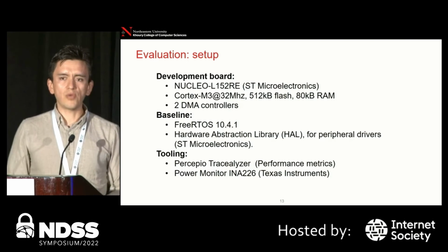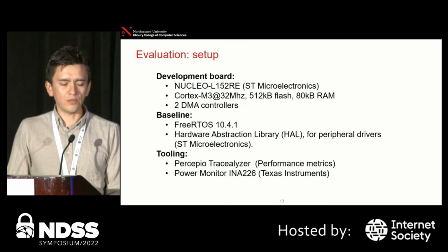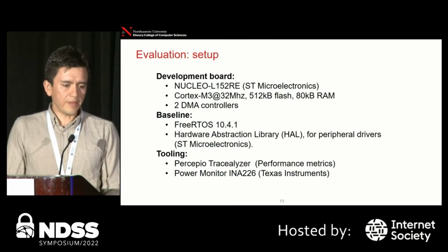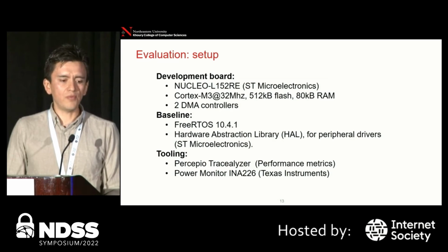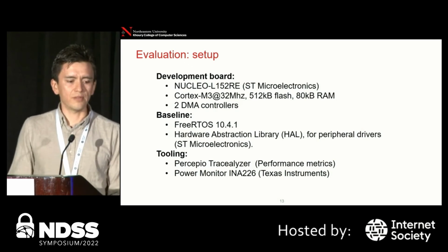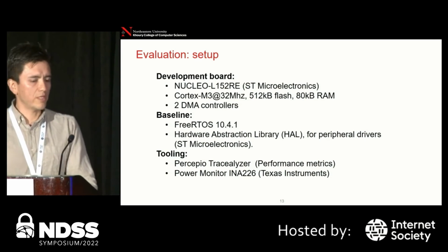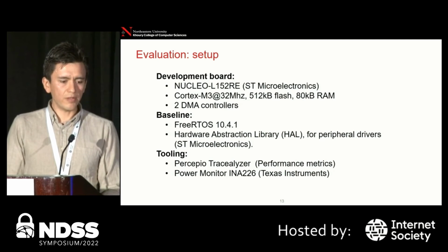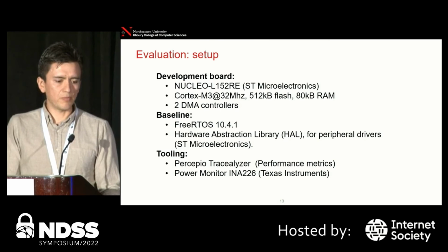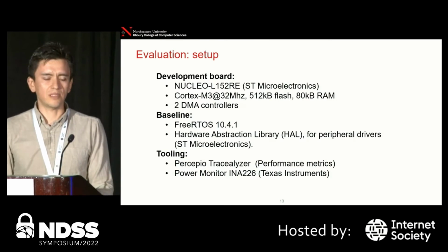The baseline that we compare to is the vanilla FreeRTOS 10.4.1 and the hardware abstraction library for peripherals that is also provided by ST Microelectronics. The tooling that we include to collect performance metrics is the Percepio Tracealyzer, and for the power monitor, the INA226 provided by Texas Instruments.